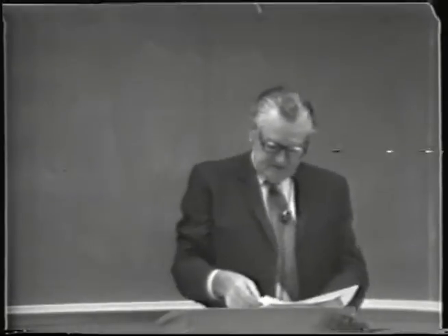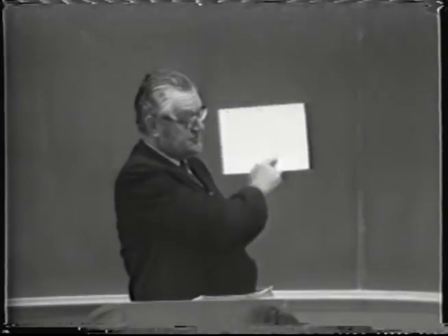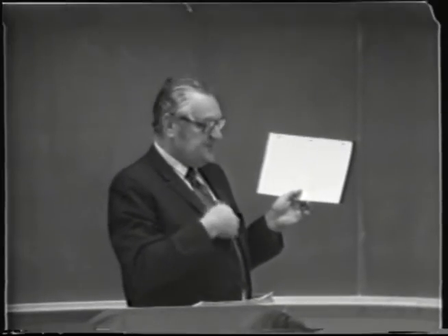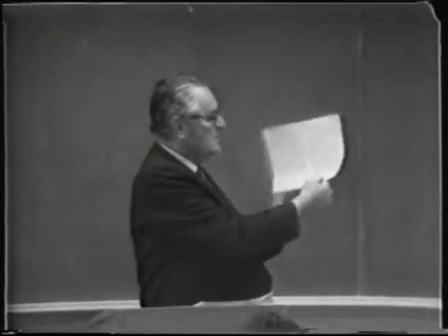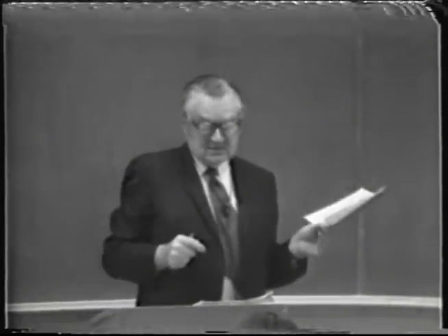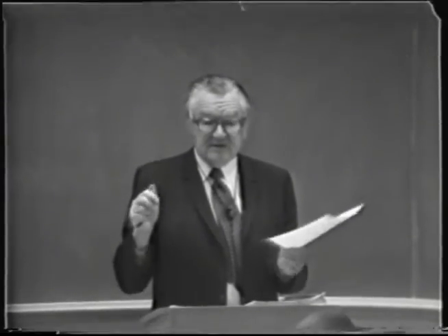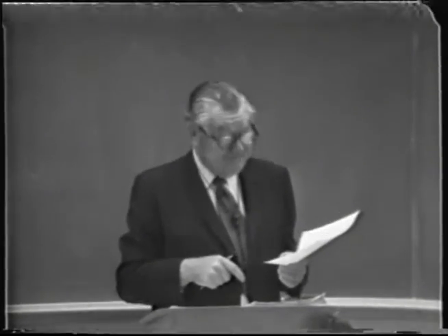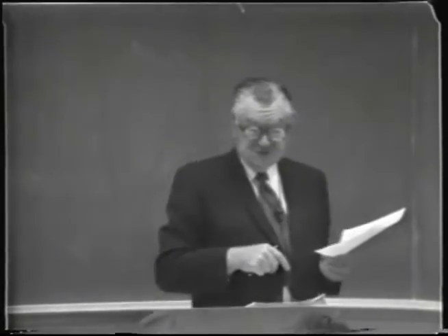So the steam jet ejector is exactly similar to this design here, in which high pressure steam is run through a jet, and the pressure is converted into velocity through this constricted jet, and therefore is dropped in pressure. And so it can draw in then in the suction position here either vapors or gases. In the case of the evaporator, we're trying to maintain the vacuum while we're pulling out non-condensable gases, dissolved air and so on, SO2, in the case of their operation down there, because they had a lot of SO2 in the juice to be concentrated.